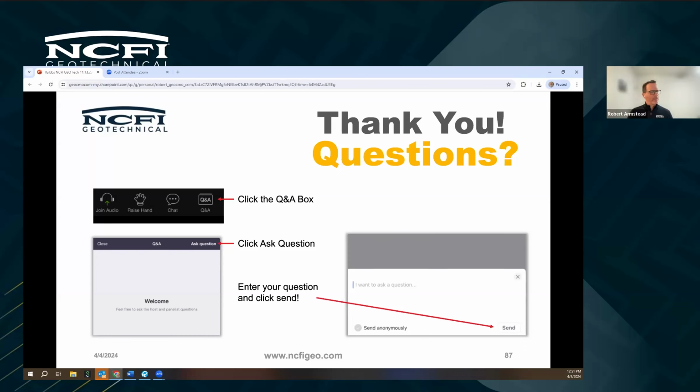This is kind of a follow-up equipment question. Can our dual component equipment be converted and used for single component applications? No. The short answer to that is no. Would it be possible to use one of those proportioning pumps to pump material? Possibly, but the equipment to do single component, it would be a huge hassle and potentially contaminate your lines and things like that.